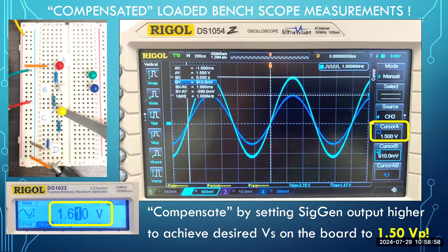But in short, if you did answer this correctly, you would have said what? These two waveforms, the dark blue one and the light blue one, what is their phase relationship? They are said to be in phase. In phase means both peak positive at the same time, both peak negative at the same time, both cross over 0 at the same time. When all of those parameters are spoken in that way, then we can say that these two waveforms are in phase. Didn't know you were going to get quizzed along the way.